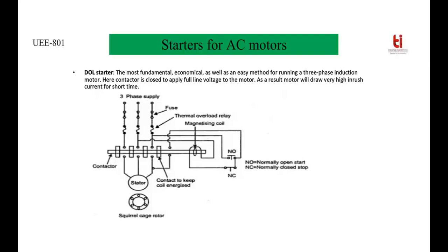You can see the right-most contactor will give a path to the magnetizing coil through the stator. The main disadvantage of this method is that initially it will draw a large amount of current. So this method is not preferred for high power rating induction motors.